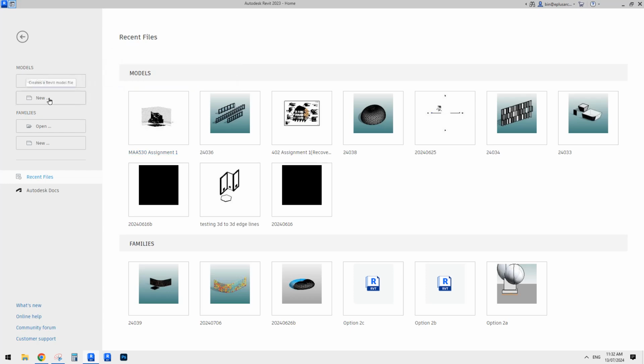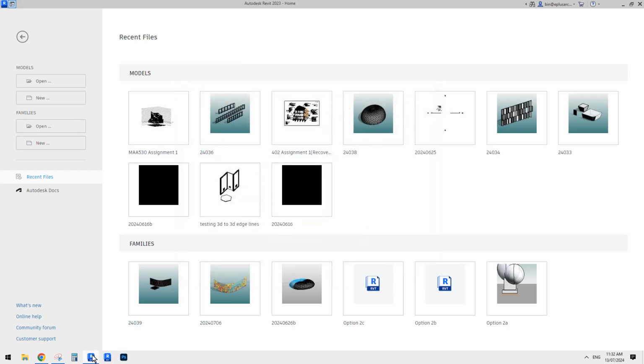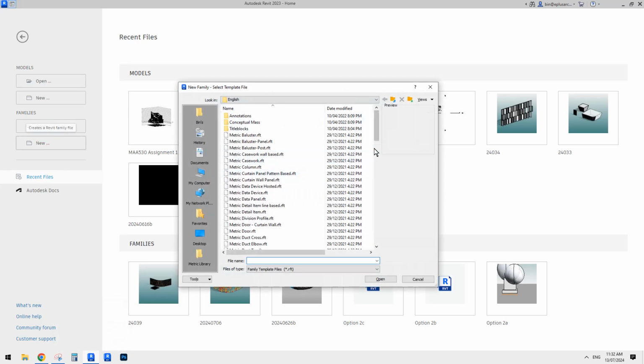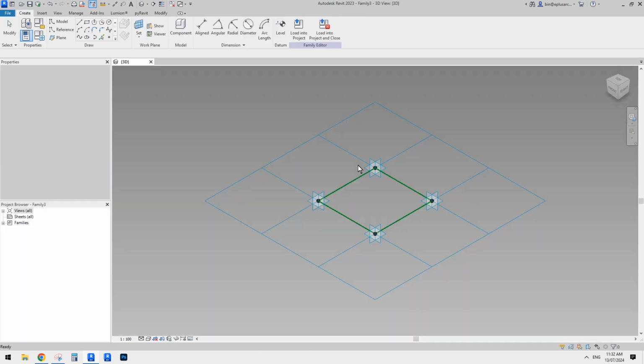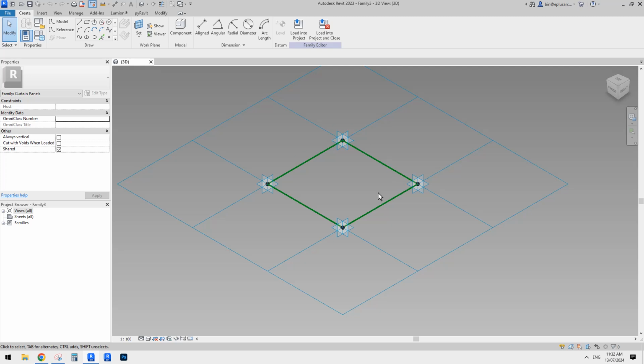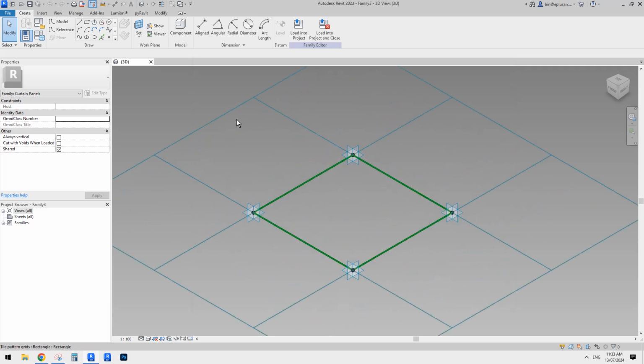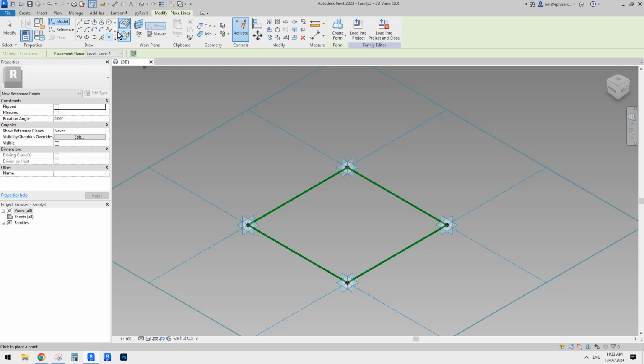Okay, so I'm going to create a pattern-based family. The pattern will be a rectangular one, so basic this one, and then we just need to add a few more, 1, 2, 3, 4, and another one in the middle. Okay, so use a point and draw on face, and then you can just directly place onto the midpoint.